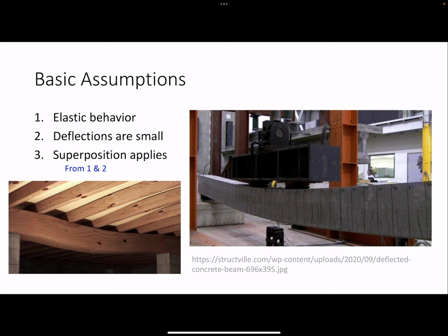We can't assume that the vertical deflections are small, for example. We have to assume a geometry under a given set of loads. But with cables, as you'll see when we get into it, we do assume that the axial deformations are small for given segments, right? So we assume that the cable segments do not change length. But again, we can't ignore the vertical deflections on a cable.